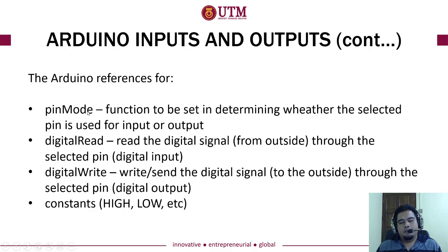And if you execute your pinMode and assign a certain port as output, then you can use the digitalWrite function to write to that port, and that port will send the signal from the Arduino to the outside. That is, you set the port as the output port.